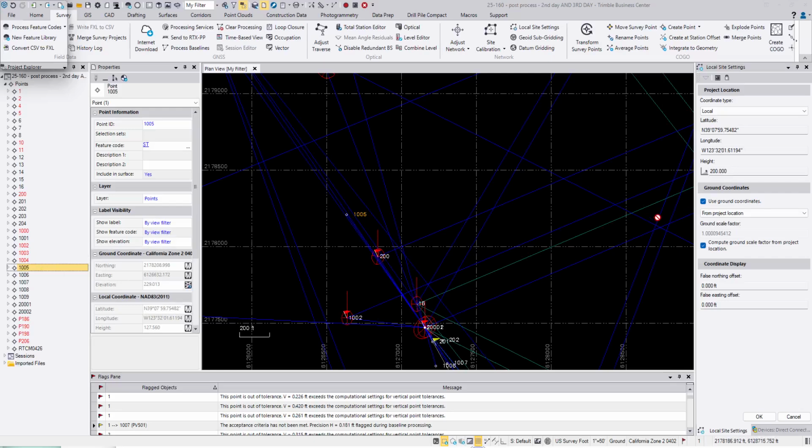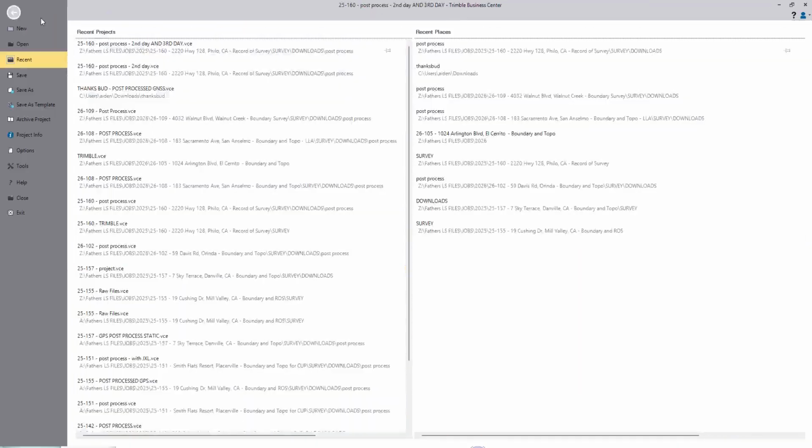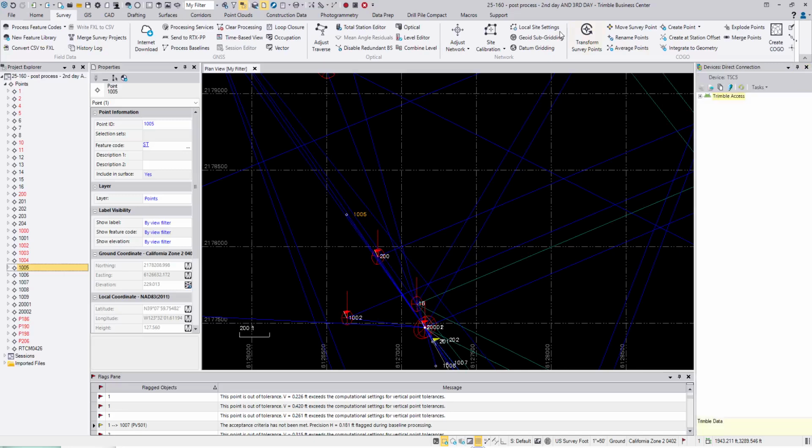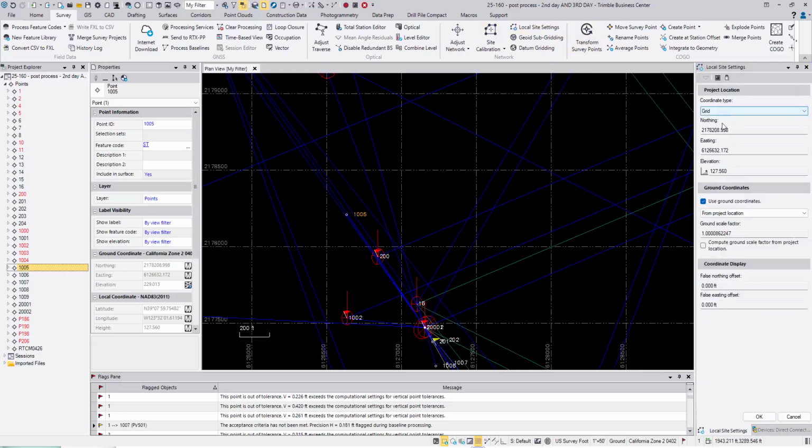All right, I'm gonna jump right into it. So this is TBC here. What you're gonna want to do is go to the survey tab, go to local site settings here. Local site settings, it'll pop up here. We're gonna change it to local.